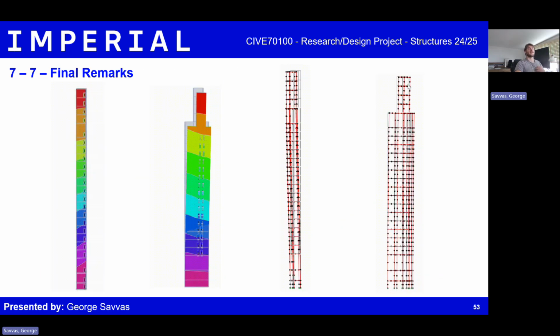Stick modeling and FE shells have consistently proven to deliver equivalent results, a fact demonstrated for decades, even in an era with far less computational power than we have today. But when dealing with more complex core geometries, precision and fine-tuning become critical, as even small variations can influence both ULS and SLS outcomes. Beyond this, the study highlighted the crucial impact of modeling openings within the shear core, as well as the practical implications of selecting an appropriate mesh size depending on the stage of the design. Altogether, these insights reinforce that accurate modeling is not just a tool, but the foundation of reliable and efficient structural design.